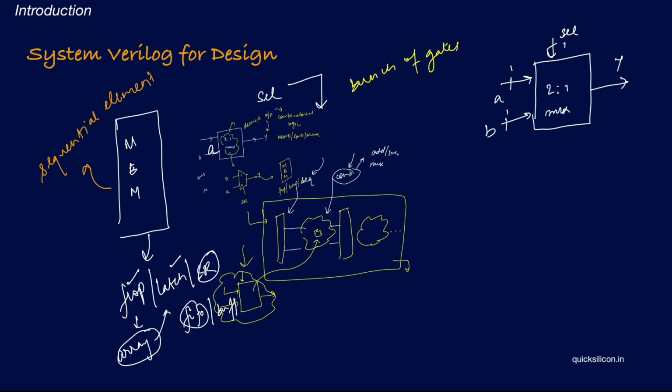In order to first do this, you need to describe this particular block, which in System Verilog is known as the module. And how you can do that is by using the module keyword followed by the name of the particular block. For this example, it would be mux 2:1. And then you can describe all of the inputs which your block takes. So here you would take three inputs, which is input A, B, and select, and produce one output, which is the Y output.